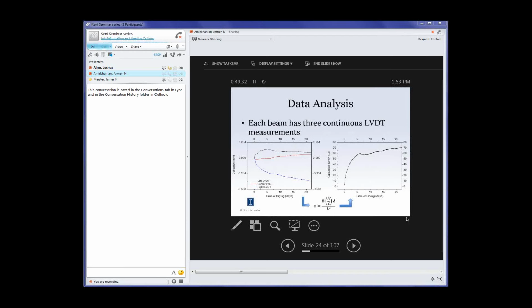I have a concern about one of the major assumptions in your study. I mean, you're doing it sidewise, right? Yes. For LVDTs. Yeah. And then you have to make the disclaimer all the time that we are not considering weight, we are not considering stresses and stuff like that. Yeah. Why not do it in the vertical direction? Because that makes this calculation very, very difficult. Because you have liftoff. That is true, but all the factors you calculate, they already incorporate the effect of weight there. Like all your equations, like C plus W, CW plus CW squared, all of that.